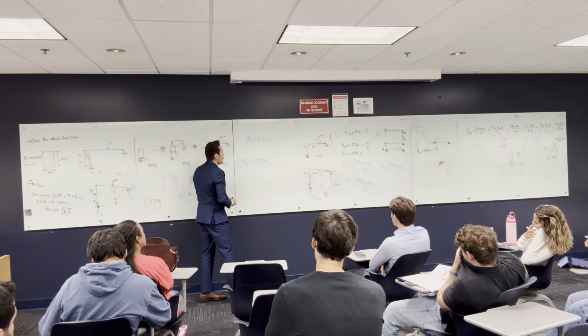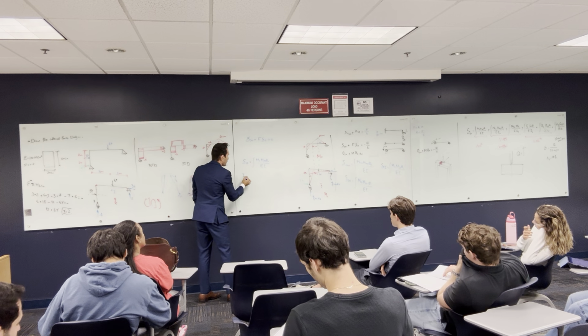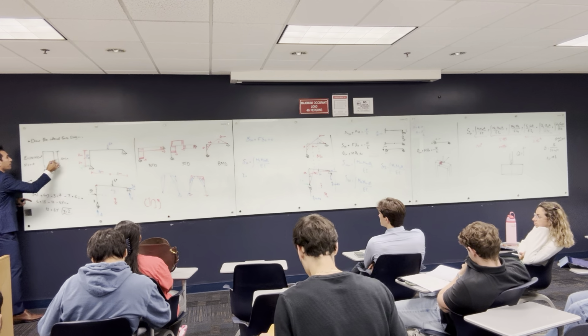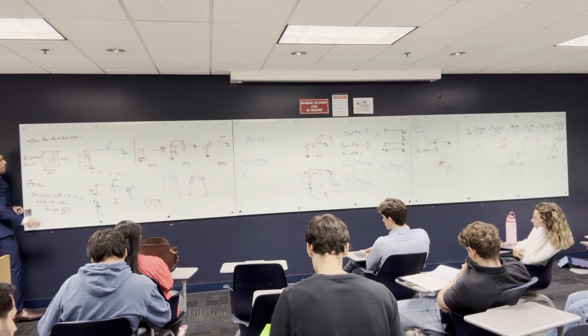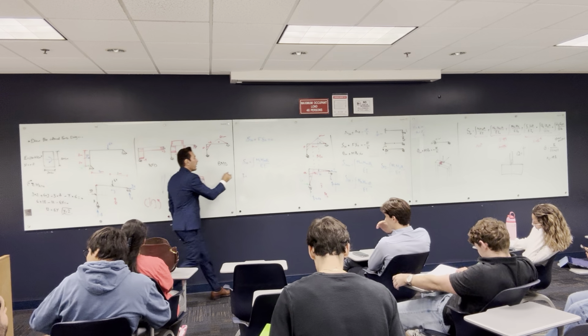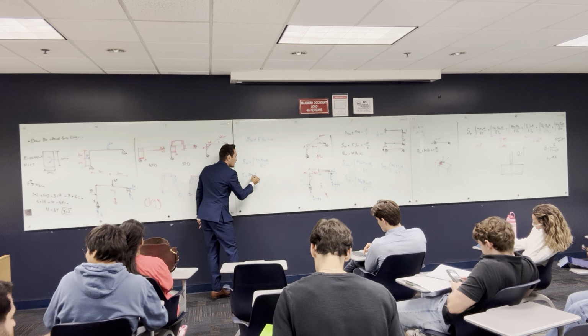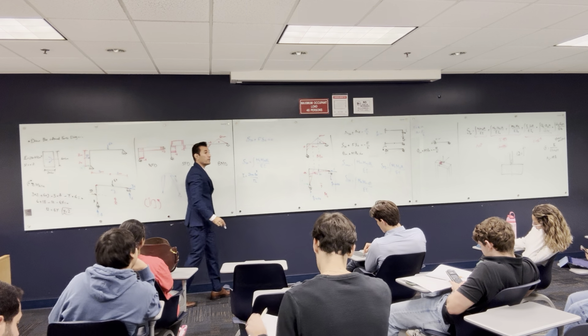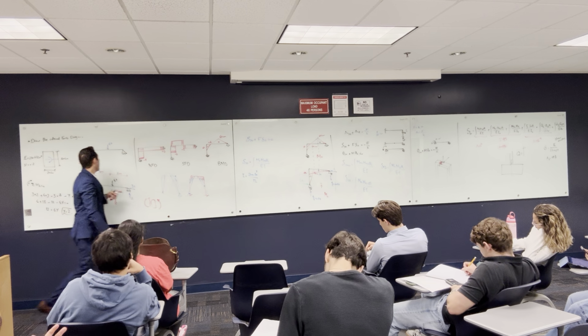All right, so I need to calculate I of the cross section. Can you guys calculate the I of the cross section? I want to find the value of I that resists that moment. It's 20 times 40 to the power 3 over 12. That is the moment of inertia of this cross section about this axis.